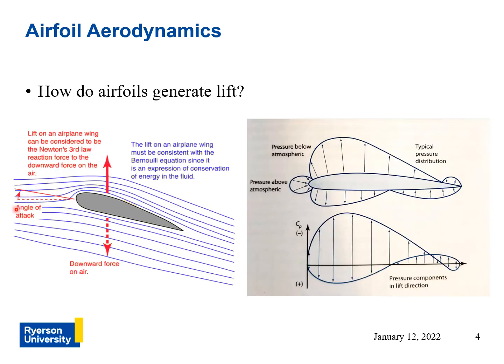So an airfoil generates lift by changing the velocity of the air passing over and under itself. And the airfoil's angle of attack and/or camber, which means curvature, causes the air over the top to travel faster than the air traveling underneath the airfoil.